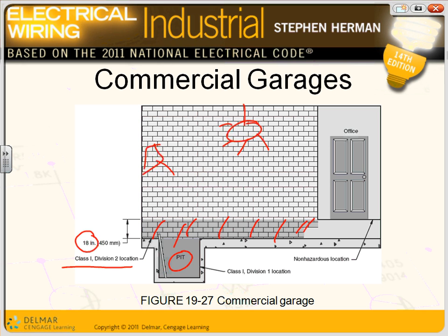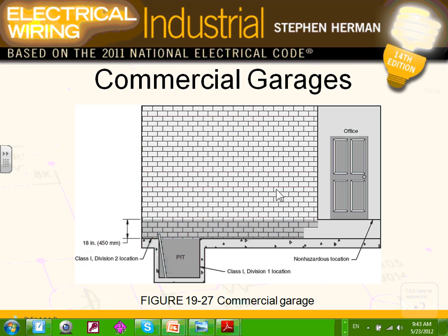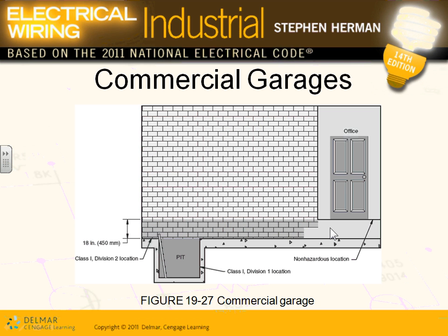So that's what I want to mention about the garages. 18 inches all over the garage is Class 1 Div 2 in every direction, and the pits are Class 1 Div 1. So whatever you install there has to meet these two criteria. And I'm not going to go there, guys. Also, you have to have a door between you and the office, and they get into how high the door is. Do you have a step up or step down to the office? So they get into a whole lot of classification.